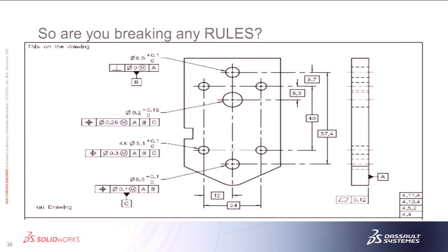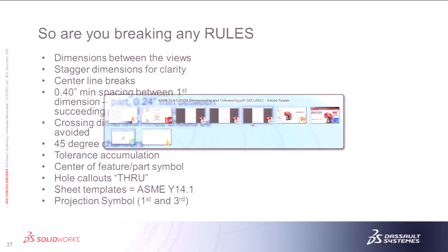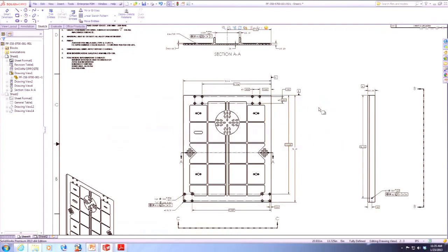It's big, it's simple, but it makes stuff so much cleaner. It goes back to the clarity and simplicity. And like I said, they grouped all the GD&T on the left side for the holes, and then they dimensioned between the front and the right side. They could put it to 12 or 24 towards the top too if they wanted to. But you should always try to dimension between views. All right, before we go any further on that, we forgot to show something earlier.